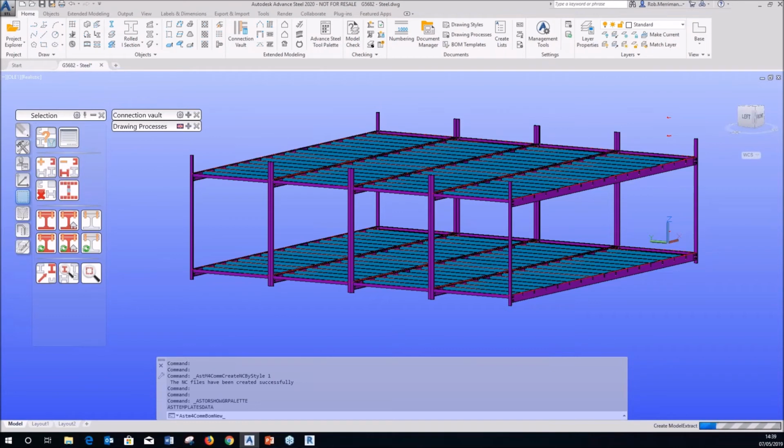So when your workshop are manufacturing, they can tick off, highlight or cross out when they've made certain bits. It helps the foreman go and actually get the pieces of steel that they need, so the yard isn't full of steelwork and they're not trying to measure and bring in all the different bits and pieces they need. If you sent it to the drill and saw line, it'll be marked with the correct shaft and fitting number anyway.